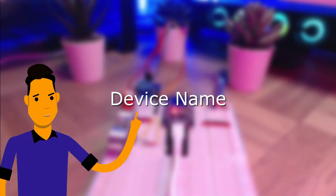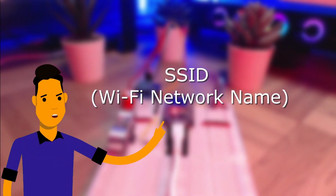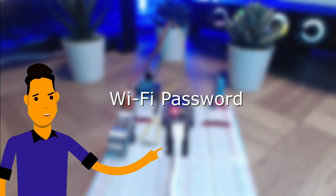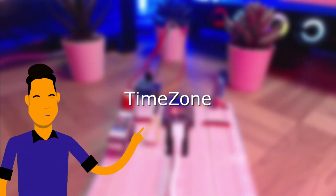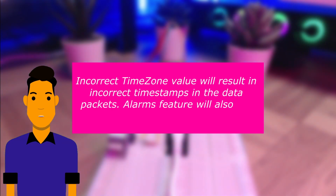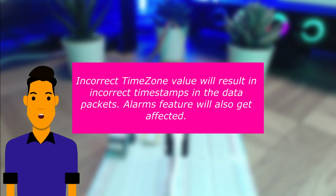The first parameter that we need to provide to ESP32 is the name of the device. The second one is the SSID, or the name of the Wi-Fi network to which we want our device to be connected. The third one is the Wi-Fi password. And the fourth one is the time zone value. Now, if you are in India, you have to use a value of 5.5 because the Indian standard time is GMT plus 5:30. For anybody outside India, you will have to use the correct value as per your local time zone.